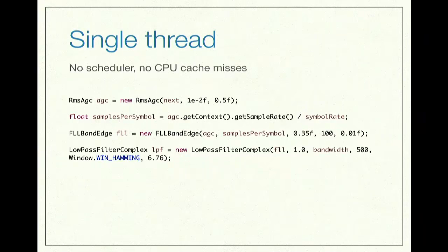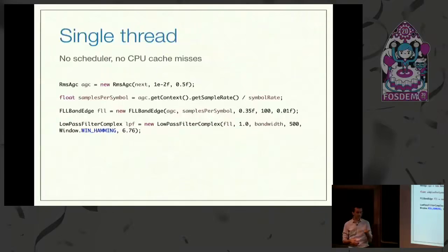And another reason why I chose this is that I would like to run it on a Raspberry Pi. And on a Raspberry Pi we have 4 cores. So 1 core would be allocated for r2cloud. The second core would be allocated to demodulating and decoding. The third core might be allocated to some system-wide operations. And the fourth core might be just in case.